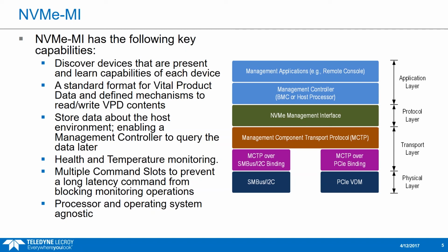Another advantage of NVMe Management Interface is that there are multiple command slots. So long latency commands are prevented from blocking operations. So it's possible to issue multiple commands at the same time. The other advantage here is it's agnostic to the processor and operating system. So the management interface isn't necessarily working under Windows or Linux or the operating system on the server, but it can be managed remotely via a separate interface.